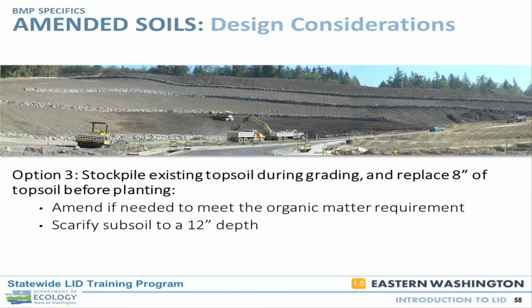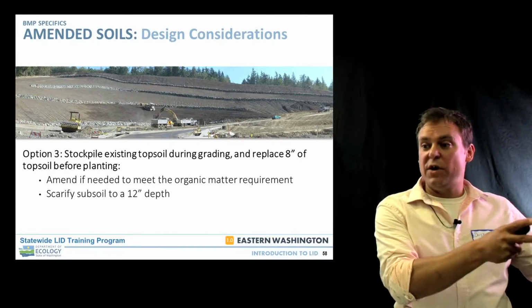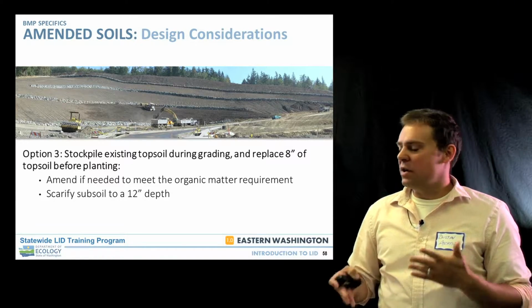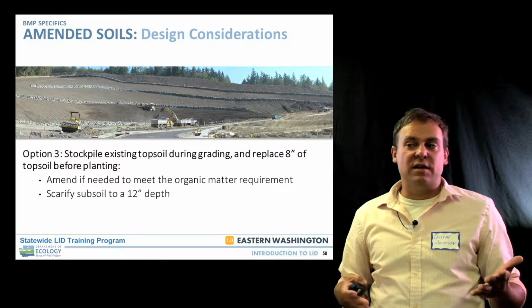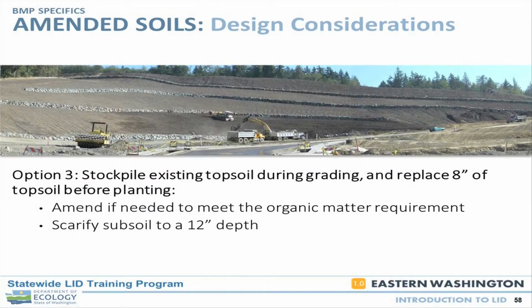Option 3 is to strip the site but keep the topsoil on site. And so you strip it, you very careful staging, and then you bring it back in. That can be a very easy technique and low-cost technique, but again, it depends on the site. If you've got a very constrained site, and oftentimes that's what we're dealing with in a development site, you're trying to maximize how much you're building, this can be a difficult one to do.